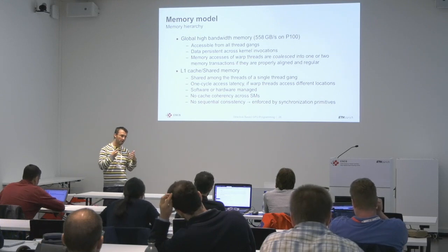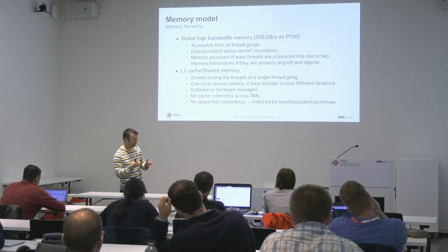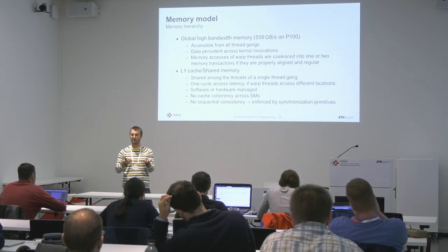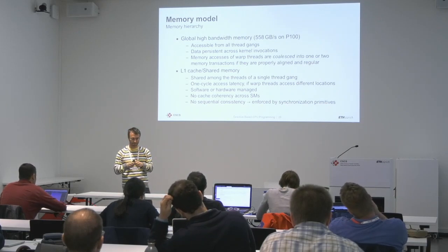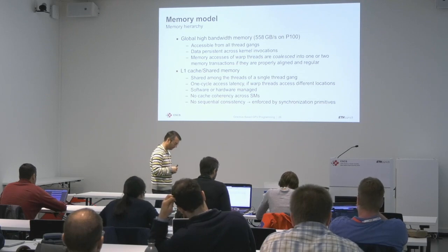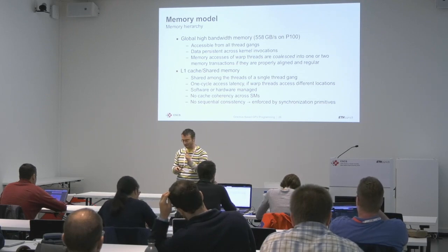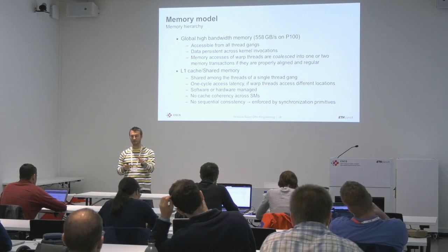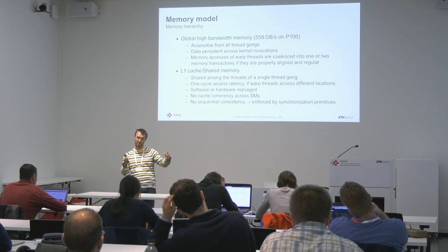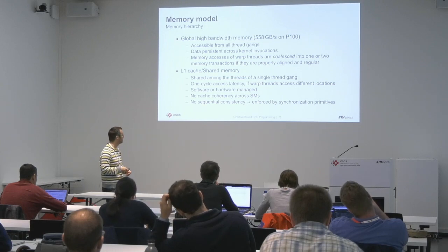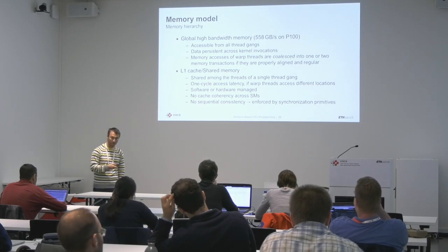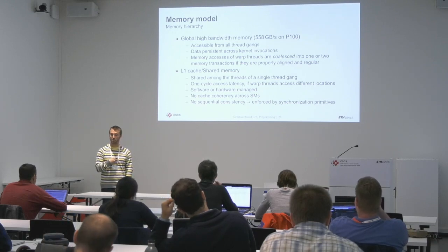But again, the common notion here between CPU and GPUs is that you need spatial locality. Now, in the GPU, it's not just spatial locality on the accesses, but it's spatial locality on the accesses across the threads. It has also this dimension of the threads. So is everything clear here? Any questions?